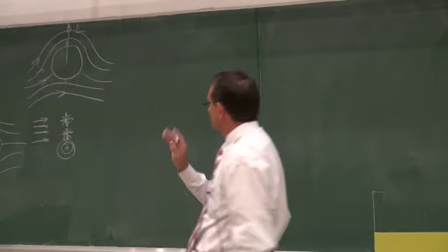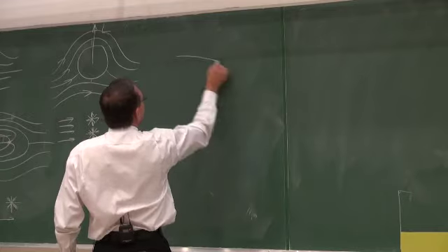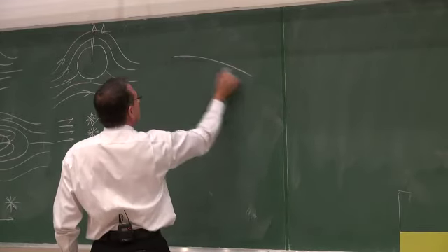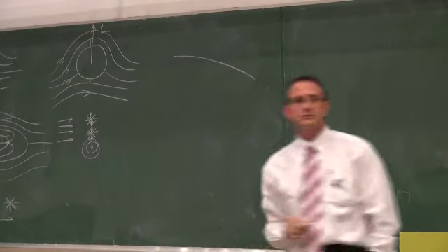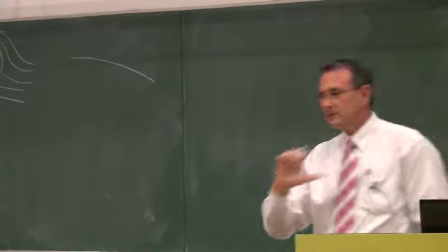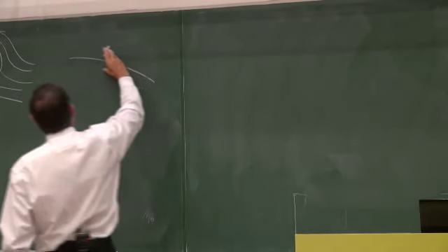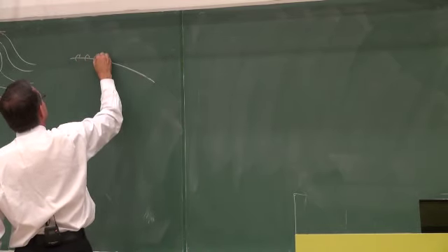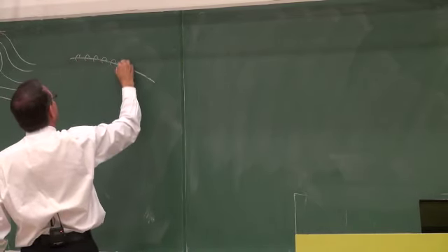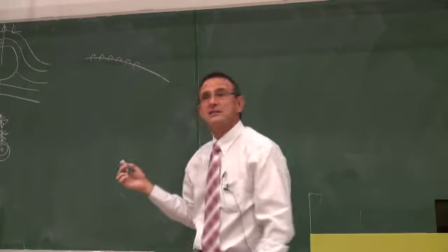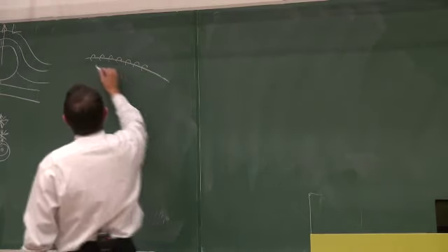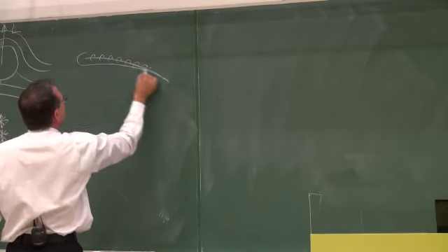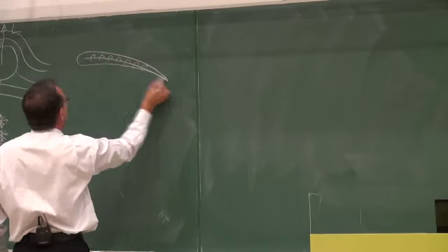And then aerofoils. What people did is they would look at, let's call it the center line of an aerofoil, and they would put lots of vortexes over this, of different strengths. And the result would be an aeroplane wing.